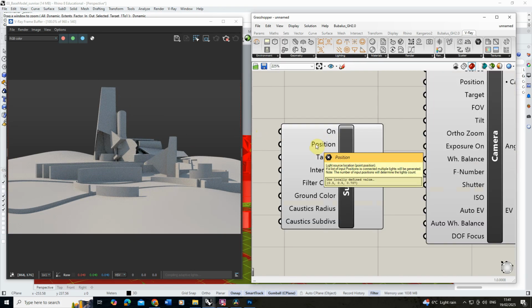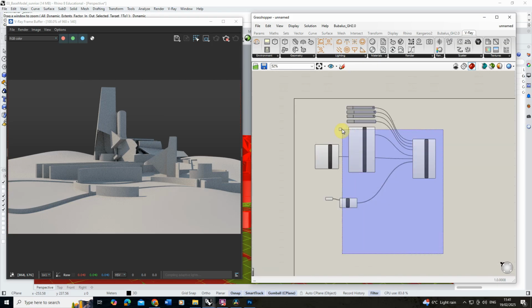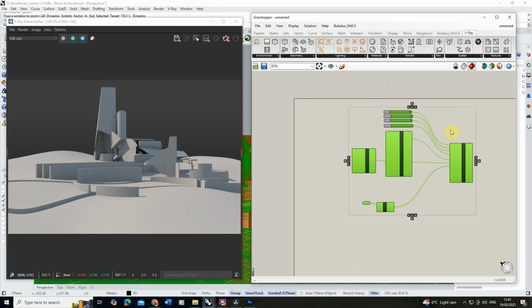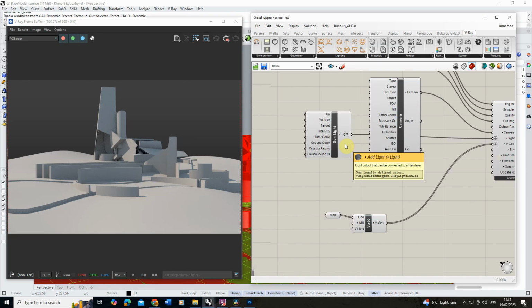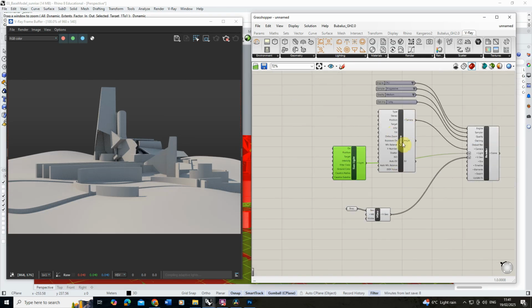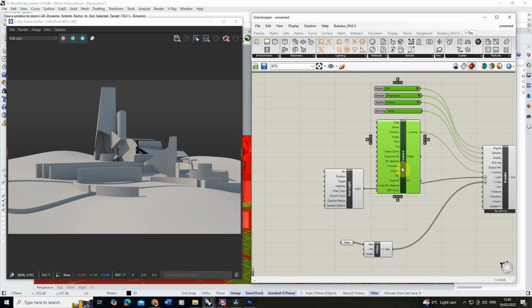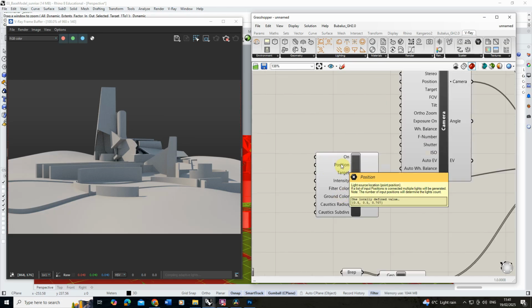Now the position of this sunlight is set by this position marker, and it has a default value to begin with, but it may be that you actually want to control that more specifically, especially if we're trying to create an animation that has the sun rising and sun setting at certain times or certain specific angles. So in order to do that, we can input a vector into this position tab to control those numbers. As you can see here, the numbers are 0.5, 0.5 and 0.707, but we can be more specific with exactly what we want those to be.